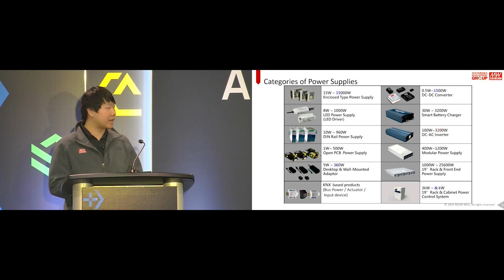Those are a type of adapters, and they're very, very cost-effective for customer applications that want to just certify their products with a DC input. They don't want to worry about AC, so they just certify their products with a 24-volt DC, and then can get a UL-listed adapter to go along with the products, and they can market worldwide if the adapter has global certifications.